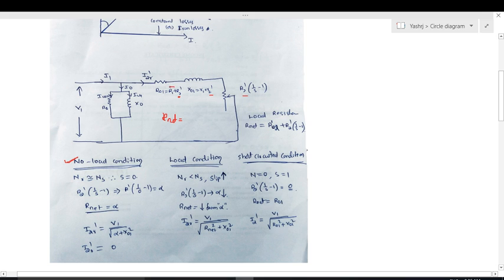But R1, the stator resistance, is very small, so I neglected it and took the net resistance as R2 dash plus R2 dash into (1 by s minus 1). Viewers, remember I'm neglecting the stator resistance because the stator winding is highly reactive. If I include R1, this becomes the gross resistance; if I remove it, this becomes the net resistance.